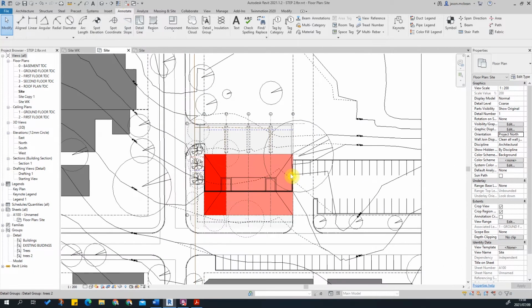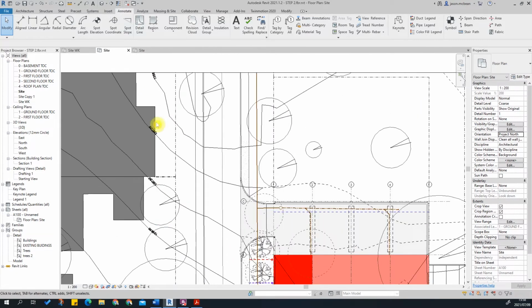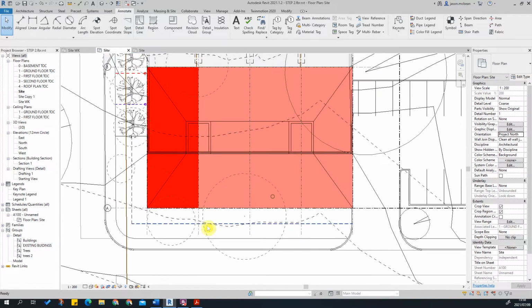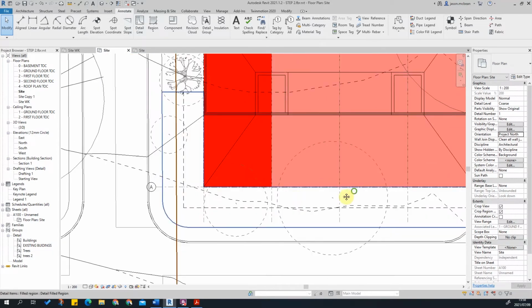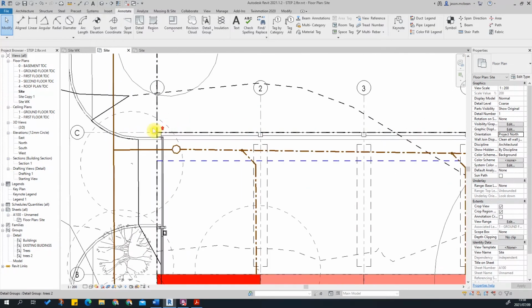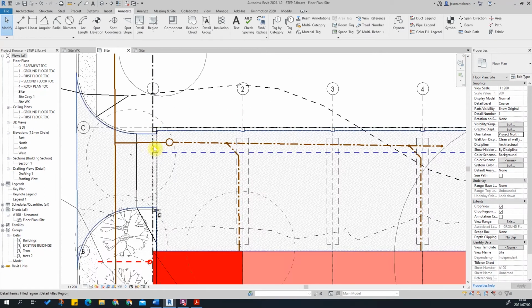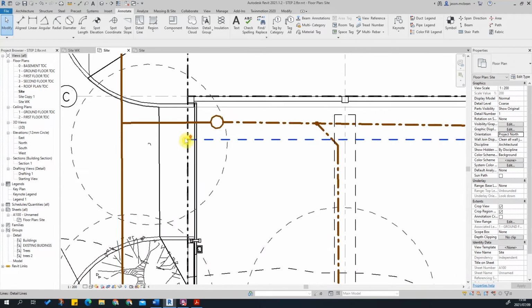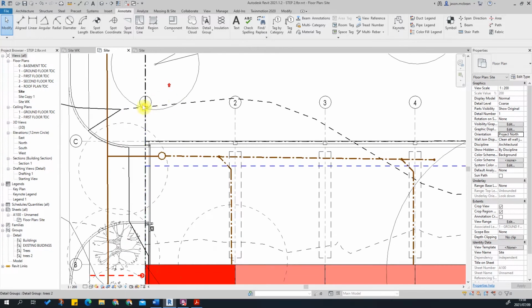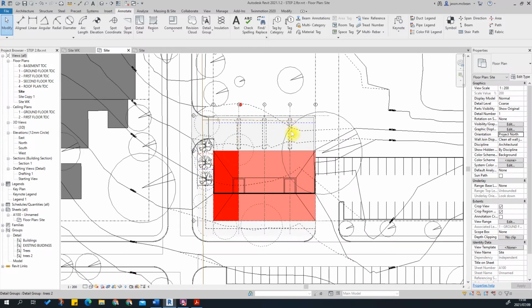Okay, so the first thing I'm going to start with is I'm going to add some basic dimensions. And then we're going to start adding a series of text. So you can see we need to add some text values for the contours, for example, the corner positions of where the site information, where the cadastral information terminates. And I've got an example of what that must look like. I'll show you that now. Okay, and we've got to address the way the grids look, etc.